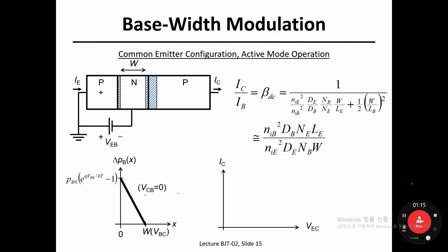So what is the core part and main topic of the short channel effect? Can you remember it? Yes, as the channel length L decreases, the threshold voltage has decreased, so that off-state leakage current has been exponentially increasing, which needs to be addressed in the end.